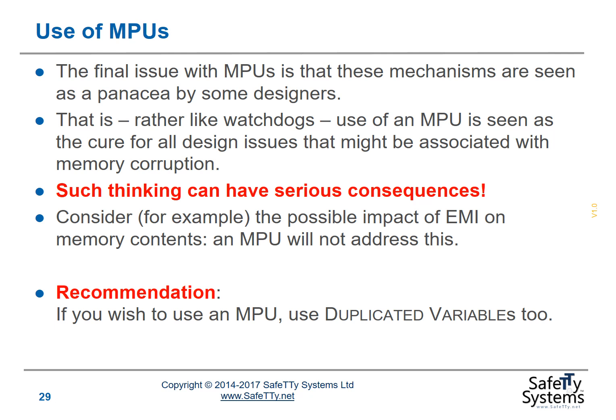Another issue with MPUs is that these mechanisms are seen as a magical cure, a panacea, a cure-all by some designers. This is rather like watchdogs. People think that an MPU is a cure for all design issues that might be associated with memory corruption. This can be very dangerous.